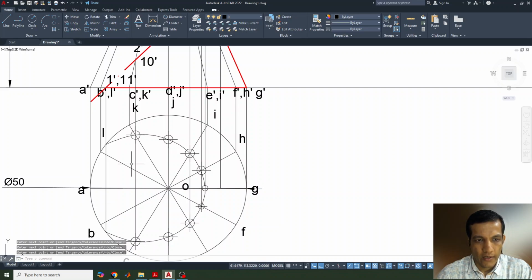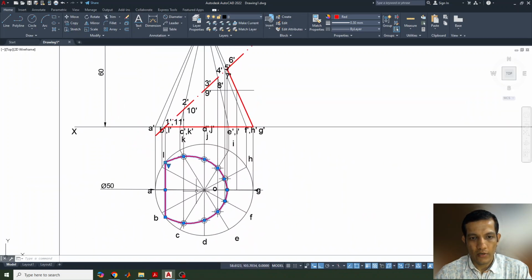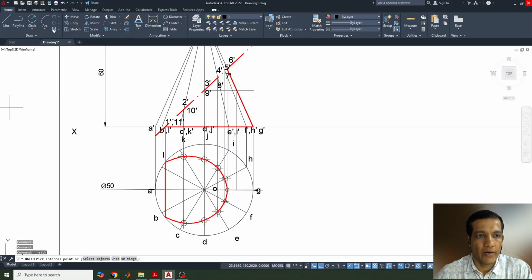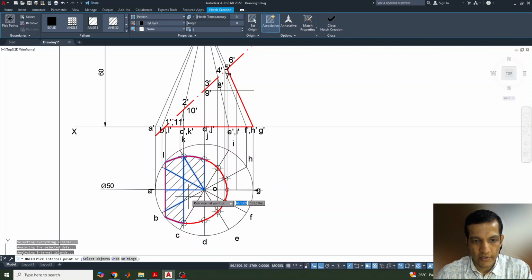Just enter it. Now what I'll do is I'll just select this one and select this R. I'll just highlight this, I'll change its color and highlight this one. Now this is the top sectional view actually. Okay, and now we need to go for hatching. So I'll select the hatching part here and select the object and just keep it, whatever hatching we want to do for all this, just click it in all these places.